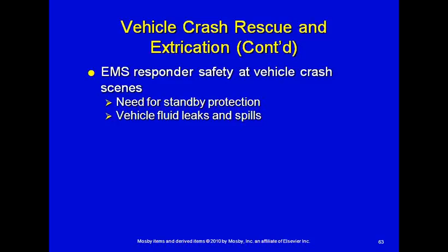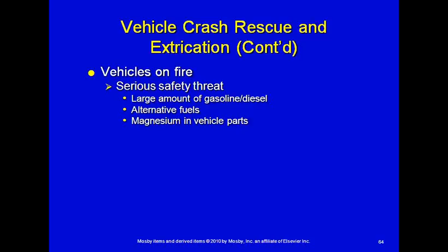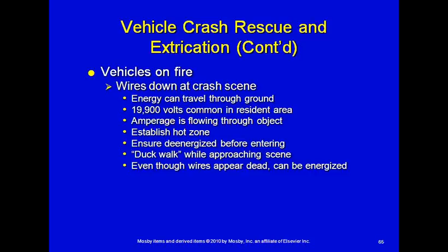Know when you need standby. Know when you have fluids leaking from motor vehicles, that those are potentially hazardous, as well as the likelihood of explosion certainly could occur, especially if we're dealing with gasoline. So large amounts of gasoline or diesel fuel or alternative fuels or magnesium, when it mixes with water, certainly can generate a tremendous amount of heat as well. So these are things that you need to keep in mind to keep the scene safe.